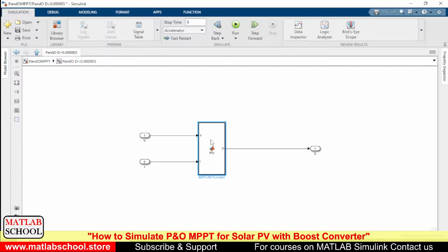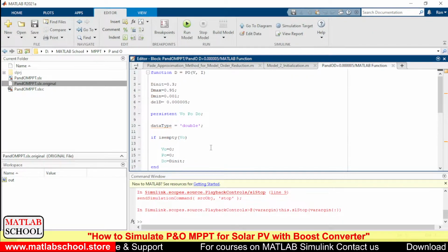Okay, so here we have the coding. As I told you earlier, we are measuring the voltage and current, and this is the initial value of pulse width, and this is the maximum value of pulse width, and 0.001 is the minimum value of pulse width. And del D is a small change in pulse width. So if it has to be incremented, it will be incremented by a value of 0.00005, and if it has to be decremented, again it will be decremented by a value of 0.00005.